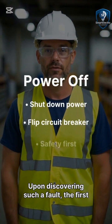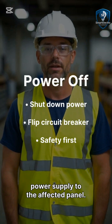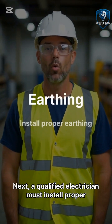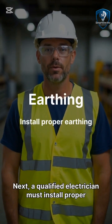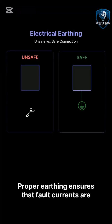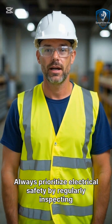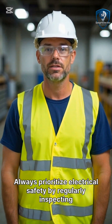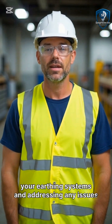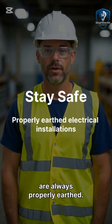Upon discovering such a fault, the first step is to immediately shut down the power supply to the affected panel. Next, a qualified electrician must install proper earthing to ensure the panel is safe for operation. Proper earthing ensures that fault currents are safely discharged, protecting lives and equipment. Always prioritize electrical safety by regularly inspecting your earthing systems and addressing any issues promptly. Stay safe and ensure your electrical installations are always properly earthed.